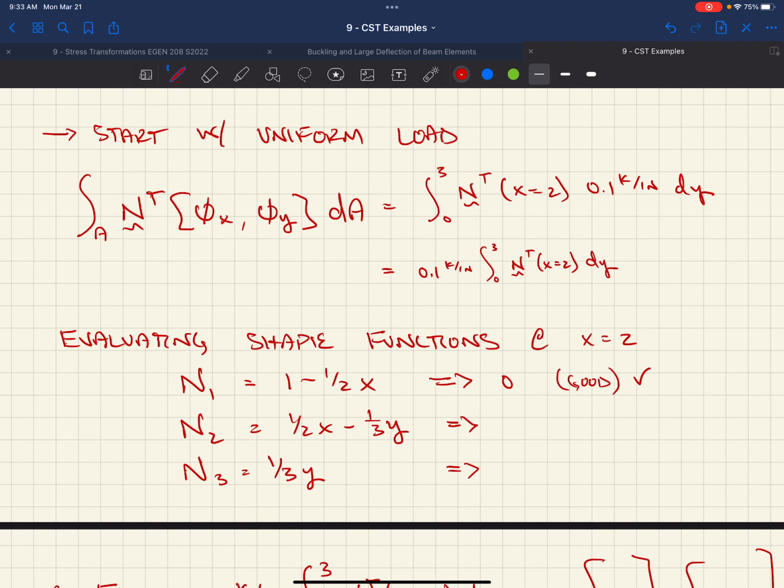If the loads are only acting along the line that is between nodes 2 and 3, we shouldn't have any forces that come from those applied loads that act at N1. Or similarly, these are essentially the keys that give us the relationship of what's going on in the field to what's going on at the nodes, right? Whether we start at the node and we're trying to figure out what's going on in the field, or we have something going on in the field like our loads, and we figure out what's going on at the nodes, right? And this relates to compatibility. We've talked about that before, right? In one of the homeworks, I think it's homework 2.